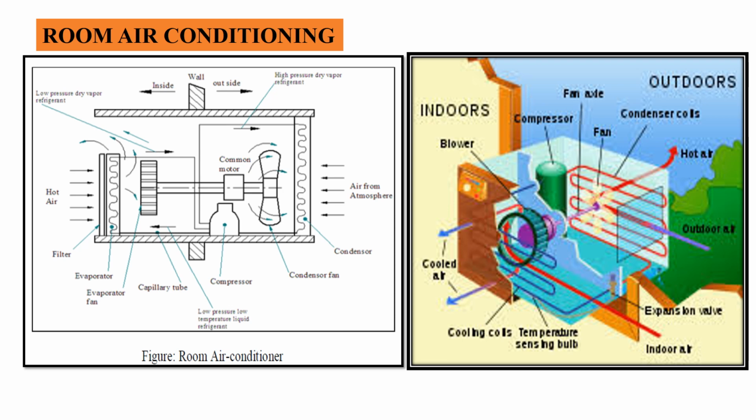What happens in the condenser? The condenser fan operates and sucks the air from the atmosphere, so that air flows over the condenser coil. The heat is carried away to the atmosphere. There is a change from vapor to liquid in the condenser, so the pressure remains constant while the temperature is reduced.